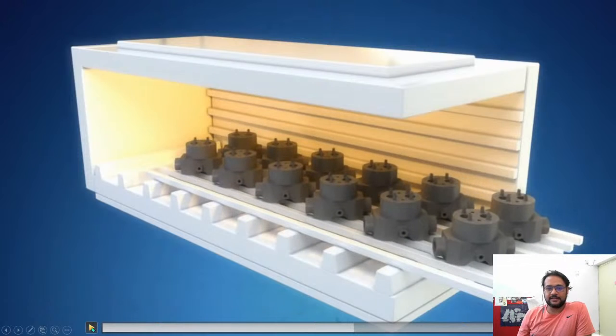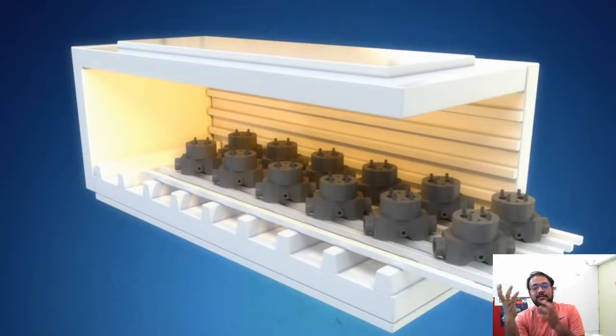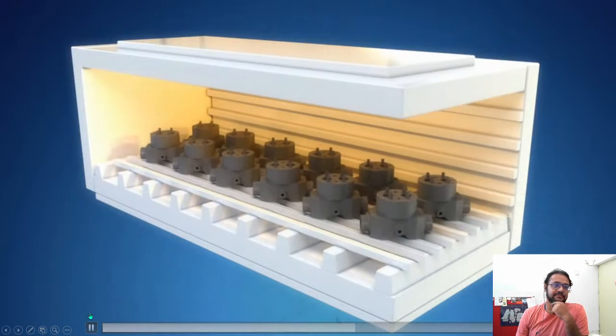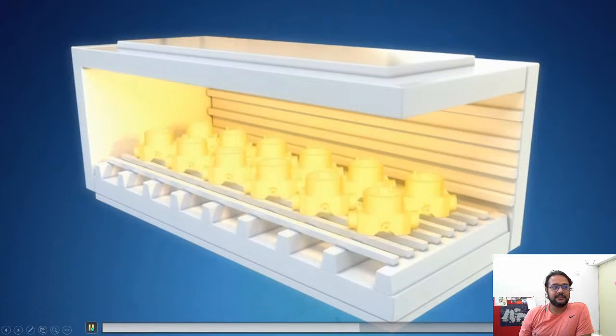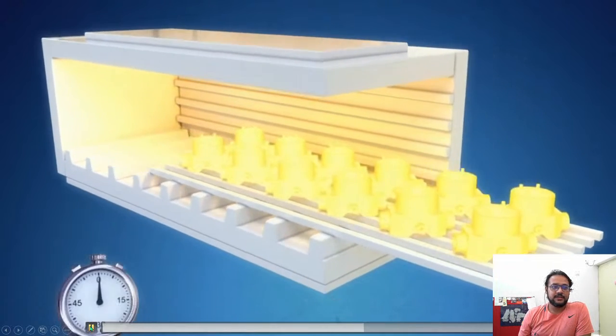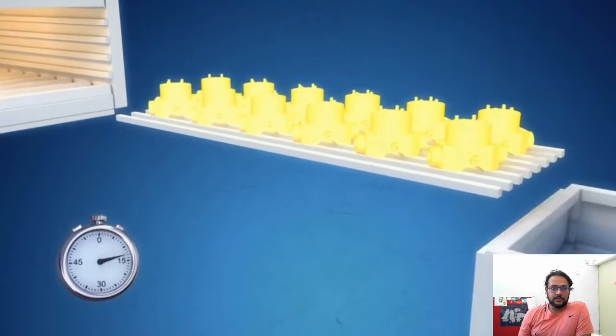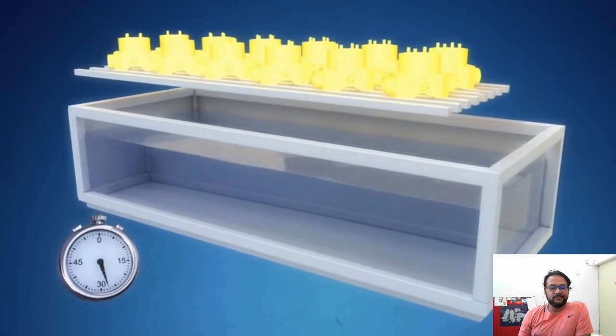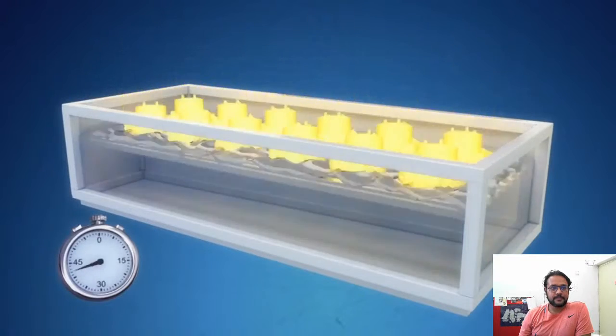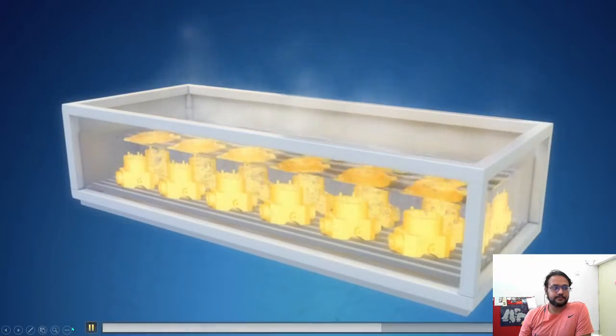So that is an interesting technical piece of information that he provided. The overall volumetric shrinkage is around 30%. So you need to design the parts in a manner that, for this kind of manufacturing process, you would need to scale it up and then make all of these shells and whatever is necessary. Okay. The HIPed material is heat treated in qualified and approved furnaces to obtain correct properties. Rapid cooling is important for many materials to ensure the required properties are attained.